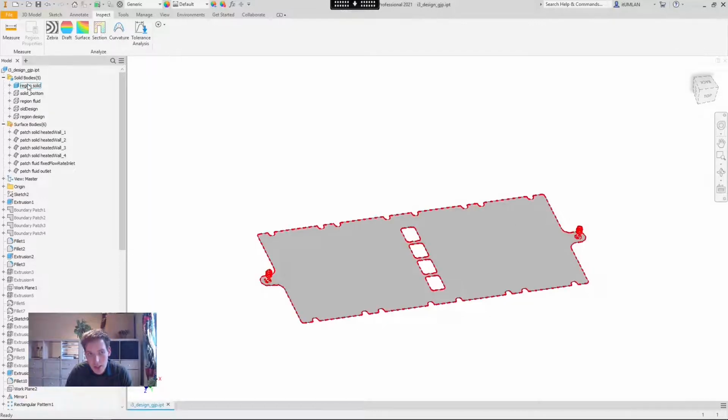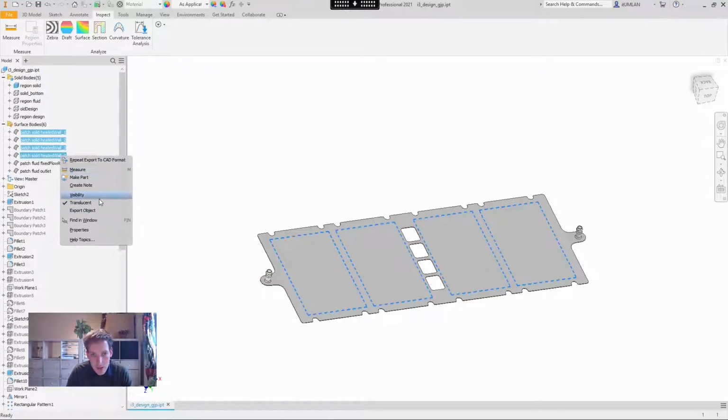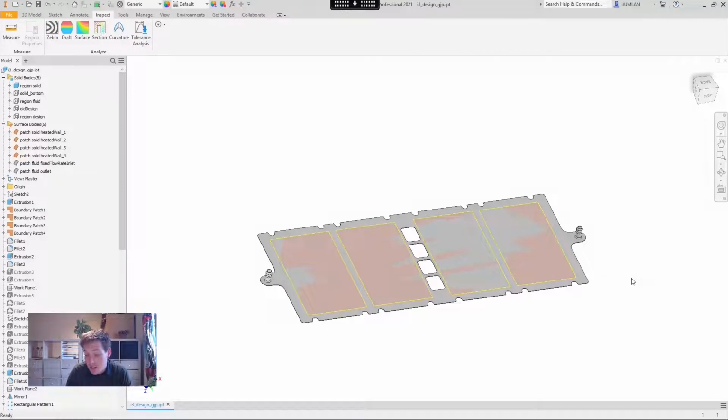That's what you can see right now. What you can see already is that we have drawn that as a volume, so really as a volumetric entity in a CAD file, as one body. And on this body, we have defined a few surfaces, four namely. Since I've said we will represent the batteries as heated walls, of course we need to indicate somewhere where these walls are located. So we do that as all separate surfaces, and we include them as well in the step file.